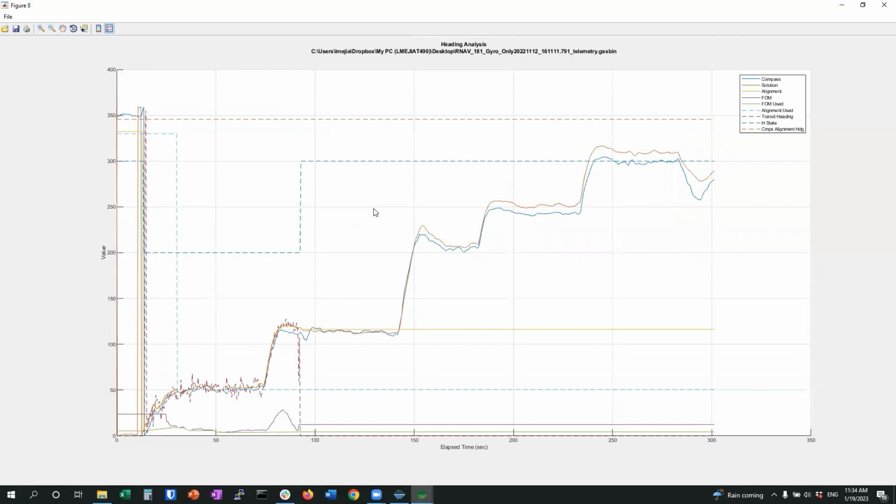One of the critical tools when we start talking about specific hardware and software issues is this screen. From here, I can look at what the compass was doing and what the INS solution is. This red line is what the RNAV was predicting for your nav solution, which you should have followed. The compass should be following it, almost mirroring and overlapping it.